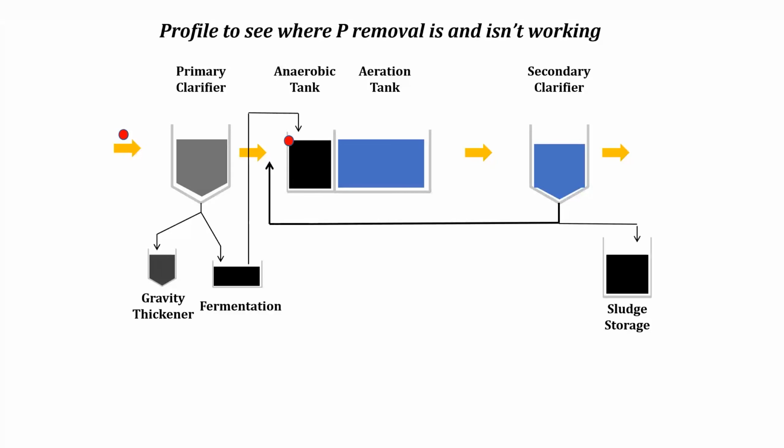That's a lot of the problem with phosphorus removal, is if the phosphorus removal is going bad, is it because the anaerobic tank's not working well, the aeration tank's not working well, or is it because it's re-releasing somewhere down? So we need some data. So let me get through this, and then I see a comment came in, and I'll jump on that.